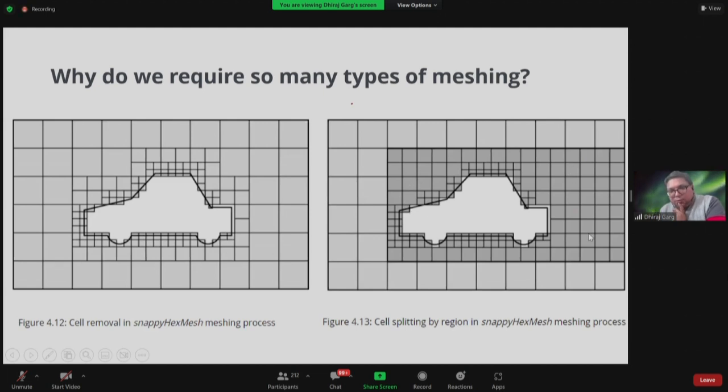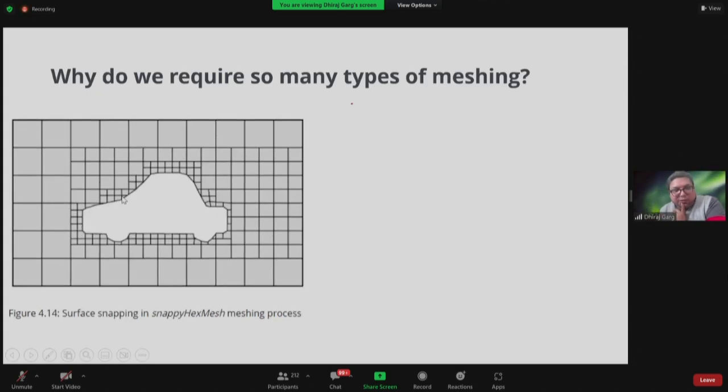Then you further restrict the area which you require meshing, and then we further refine and truncate this part. So you can see now those portions change to cover or map the geometry boundaries properly. Some portions are being removed, in the sense that those vertices are moved to the point. So a different meshing is generated. This is why you require different types of meshing.